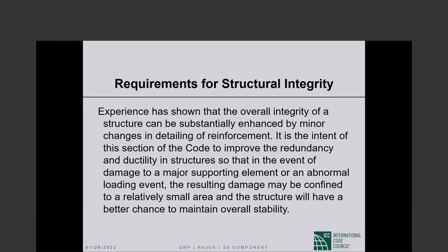You know the situation. If the top surface is exposed and the bottom surface you think is relatively more protected, you may want to place more of the reinforcement near the top surface and less near the bottom, or all near the top, but it is entirely up to you. The code doesn't restrict it. That answers almost 5 to 6 questions.